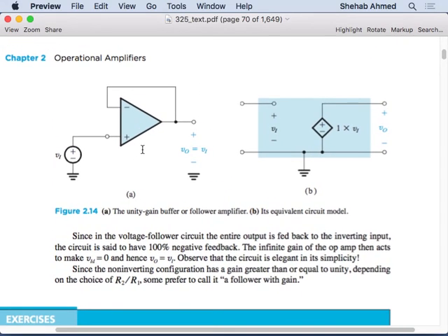But of course, we will talk about this later in the chapter. We will find, even though this is a voltage follower and we have external power supplies to supply the current flowing through this output branch, any device is current limited. Any physical system is current limited. So ideally here, according to this schematic, or according to this model, this is an ideal voltage source that will produce as much current as you require, right? But of course, practical op-amps, and next time maybe I'll try to dig up a data sheet when we talk about the limitations.